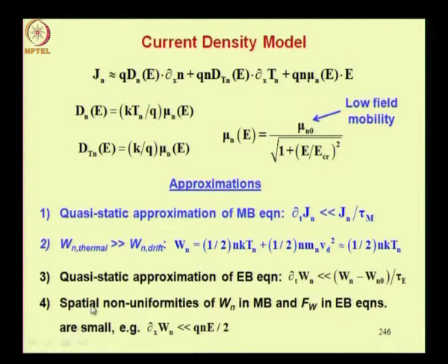Similarly, we made another approximation, namely that we assumed the conditions to be uniform when we derived this formula for mobility. You will recall that this formula for mobility involved a relation for the electron temperature in terms of the electric field, and that is where we have done the approximation that we were talking about when we derived that equation for electron temperature.